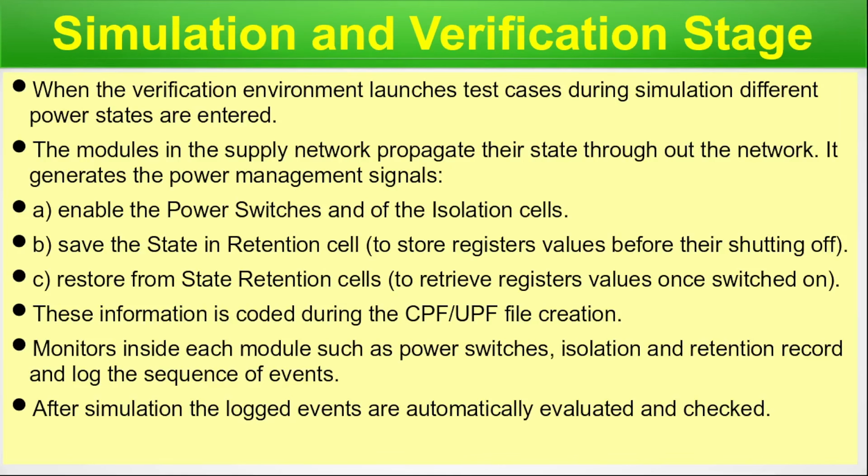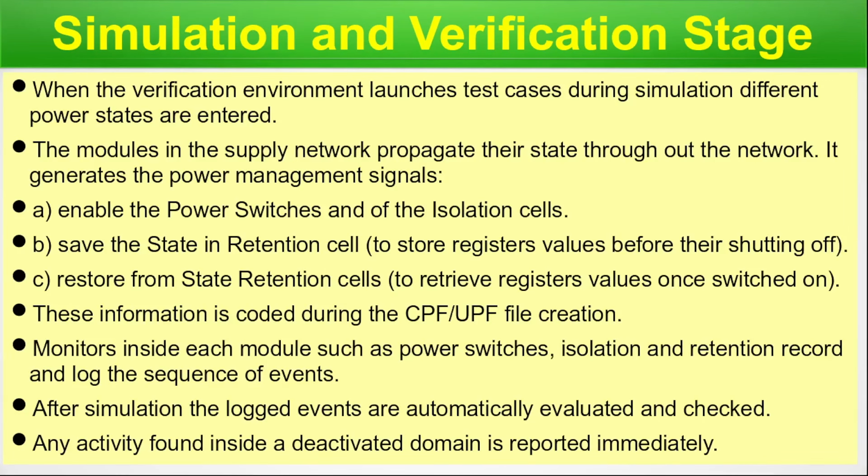After simulation, the logged events are automatically evaluated and checked. Any activity found inside a deactivated domain is immediately reported. This way, in the front-end part, retention cells are properly and thoroughly placed and checked. We are done with this particular slide, so let's move on to the next slide.